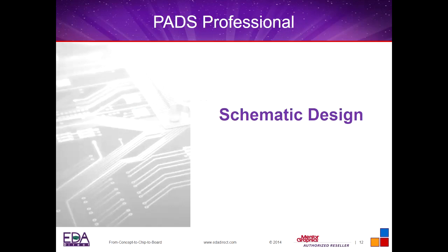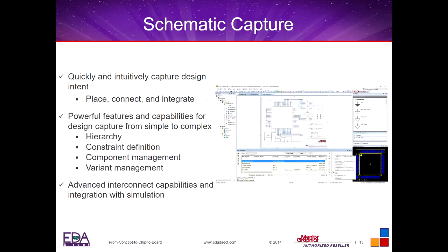Now, for schematic design, you can either use your OrCAD if you'd like, you can use Logic and stay in a netlist flow, or you can go ahead and use the DX Designer flow if you'd like, which is going to give you a lot more power using this professional tool. You can stay with the netlist flow, but to really get the bang for the buck, you're going to want to move to the DX Designer tool, to give you hierarchical design.